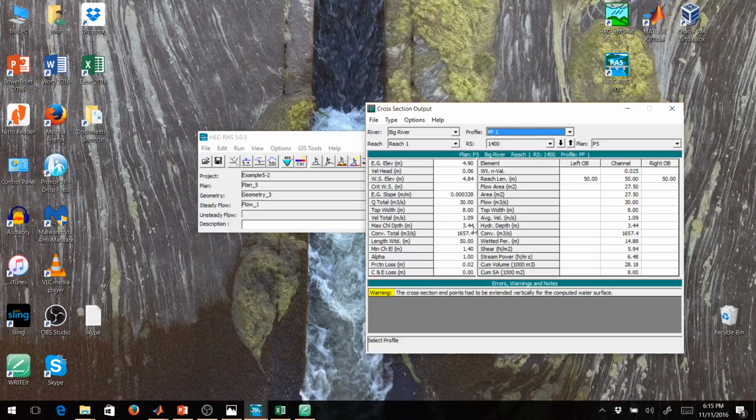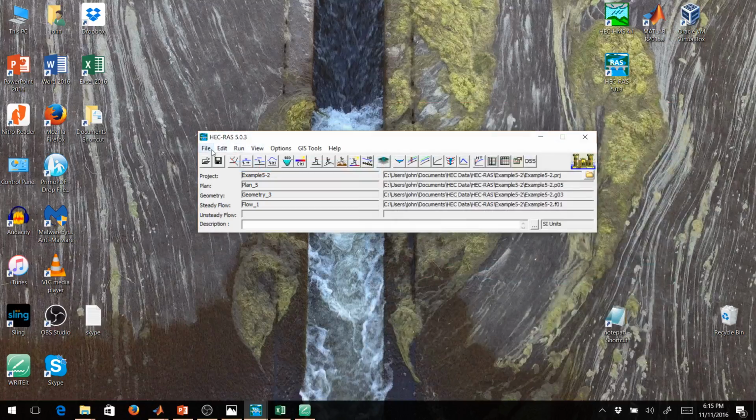So we're about 1.44 meters above that 2 meter channel that I made. And notice, again, we get that same error we saw when we ran the 60 cubic meters per second through our trapezoidal channel. So we could go back and fix that if we'd like, but I'm okay with it as a demonstration for how to put a nice, more complex geometry into HEC-RAS and how to solve it. So I'm going to go ahead and save project.